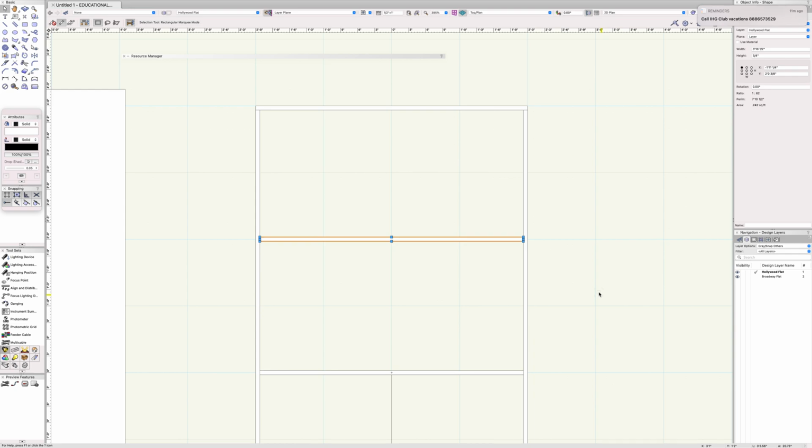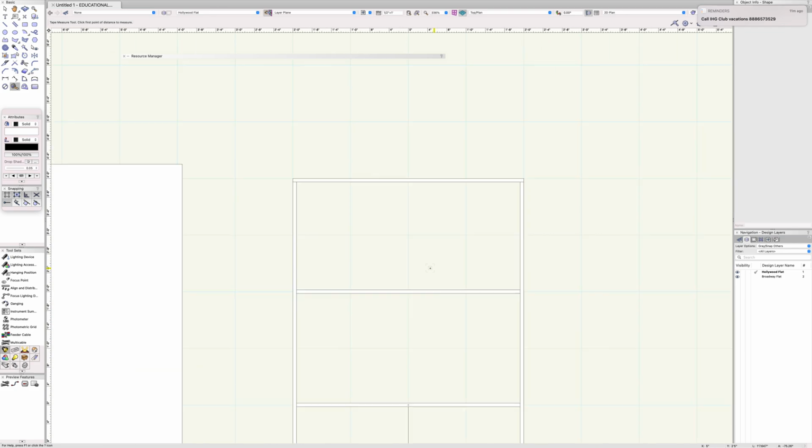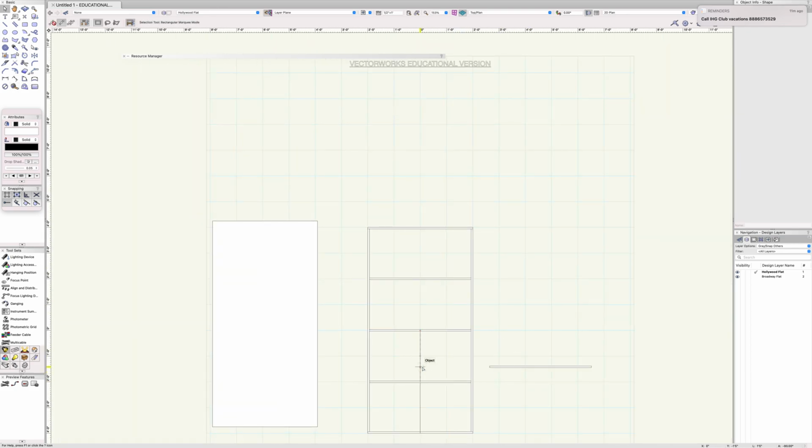Now the next toggle, I can just simply select it and Command D. This will automatically put it onto the 2 feet because this is taking the reference of the duplicate distance from the previous command. So if I want to measure this one, just to make sure that this is the correct size, I can select my scale, come on the top of the top toggle and come to the bottom of this toggle. As you see, the length is 2 feet. So I know that this is my right size of toggles placed at the right distance. So delete those lines. I don't want this one also.